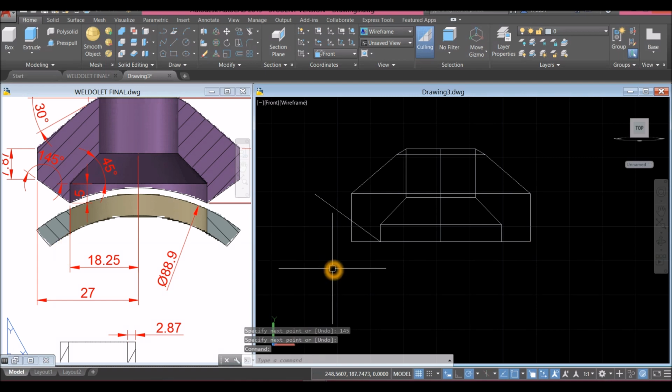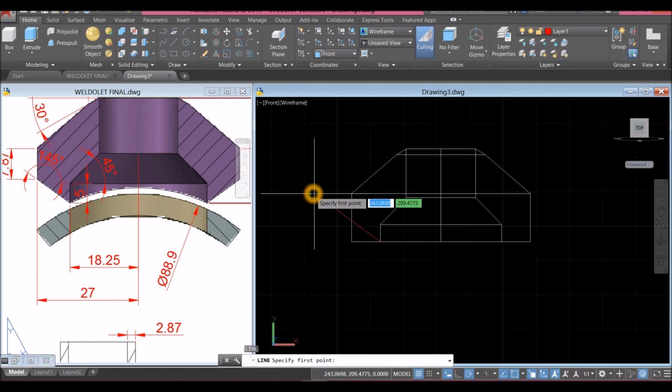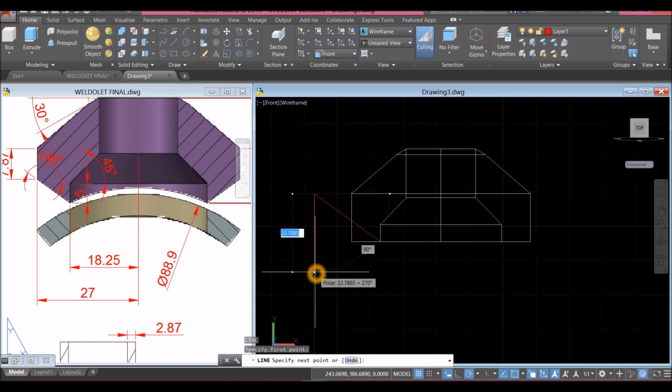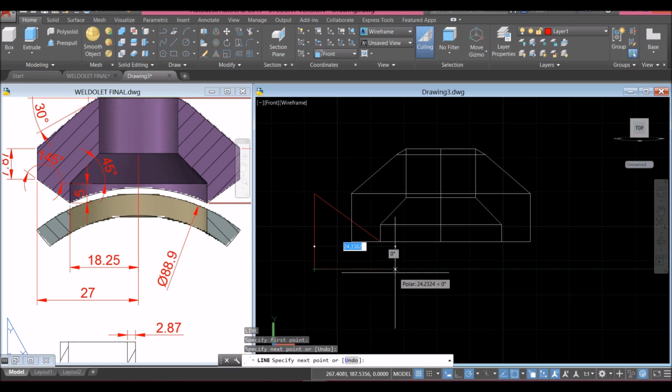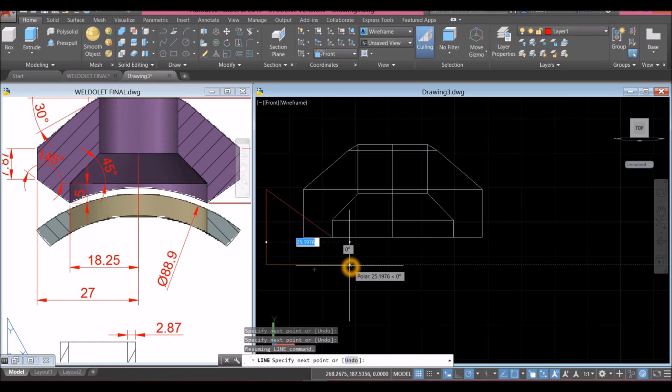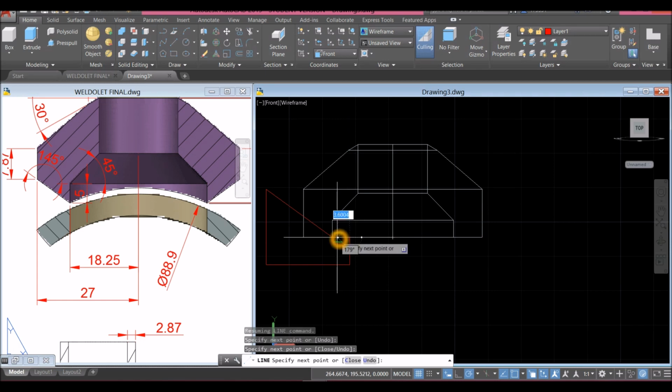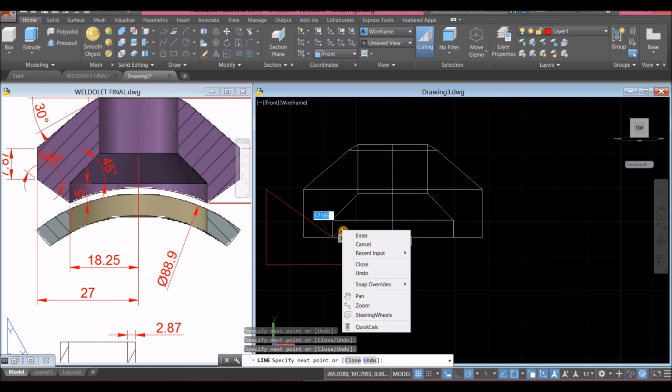Now I'm gonna draw another line. I'm just gonna use red color so it's easier to visualize, and make it current. So layer, okay, line from in point. It wouldn't matter as long as it's over the object. I just want to make sure it's not touching the edge, so it's easier to subtract. And then from here, somewhere here, hit that perpendicular point and that in point.